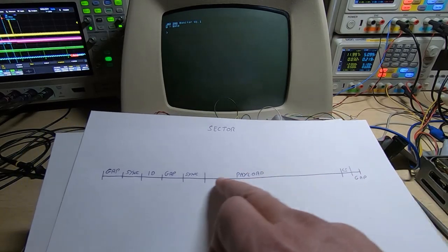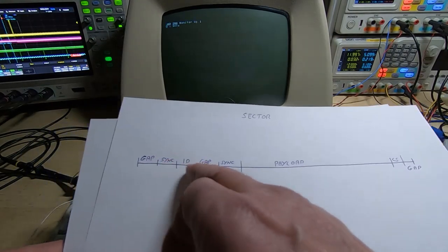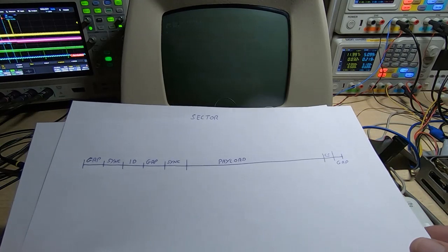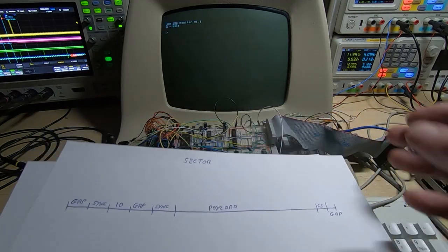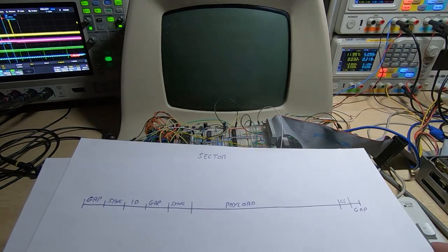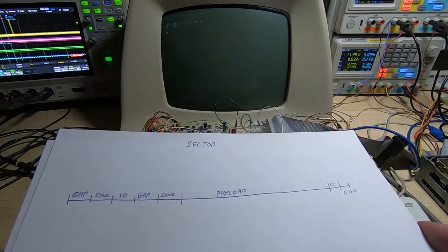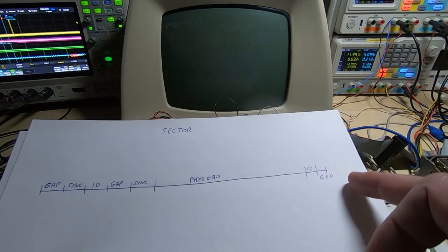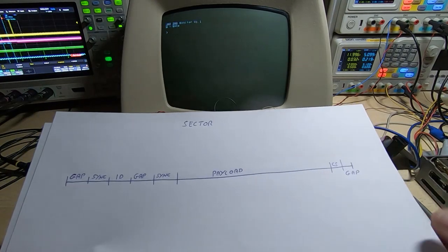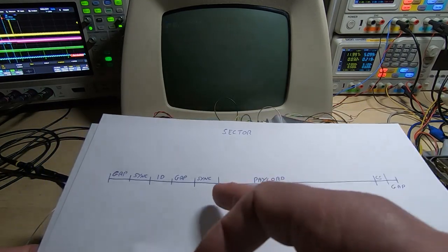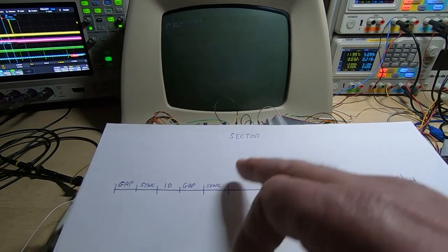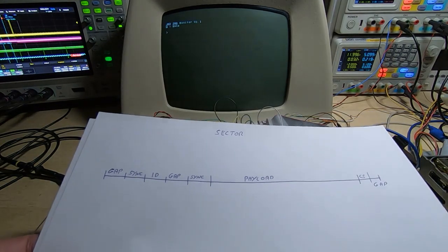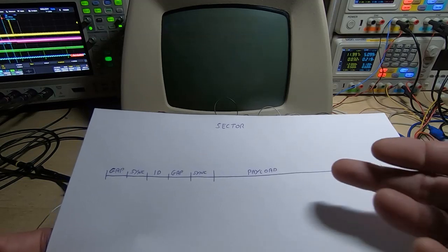So you have to write all that to the disk, and it has to be in a certain format, and it has to be done in a timely fashion to keep up with the drive system, because of course the disk is spinning continuously. If you write all this information to every sector on every track, then of course you have a formatted disk, but what you write is up to you, and there are different formatting styles and variations.